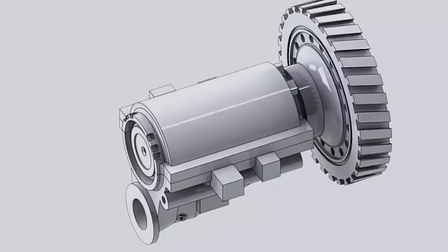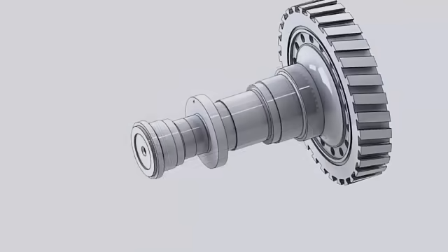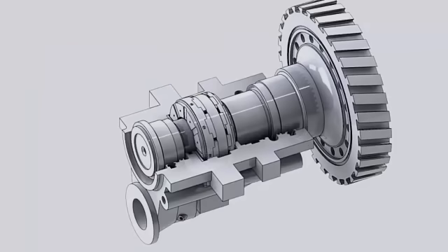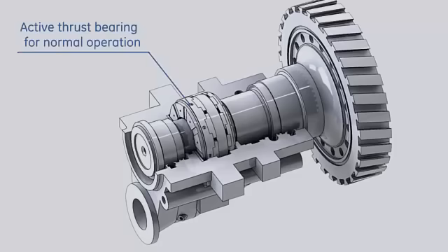The thrust-bearing major components are the thrust runner, which is integrated in the compressor rotor forward stub shaft, and 2 thrust bearings. During the normal operation of the gas turbine, the sum of axial forces induced by the airflow on the compressor stages and the hot gases flow through the turbine stages tend to move the rotor in the upstream direction, so that the active thrust bearing is located on the forward side of the thrust runner.